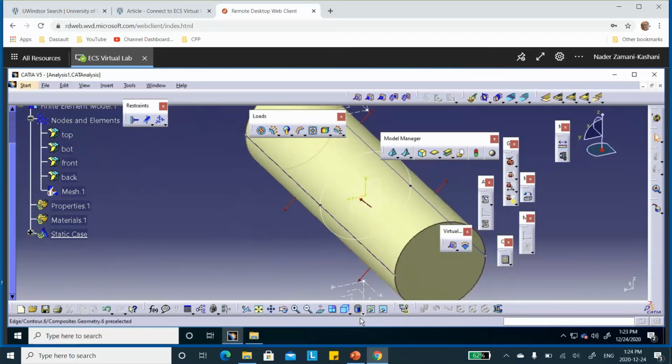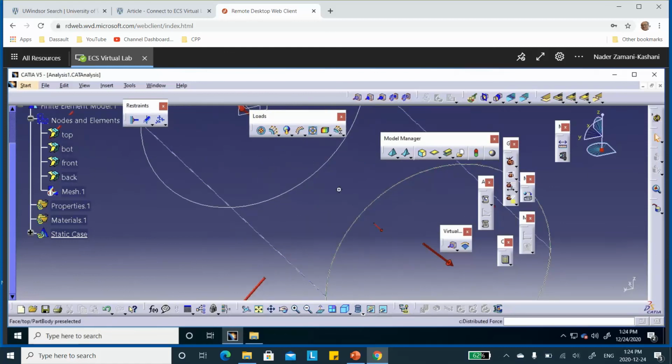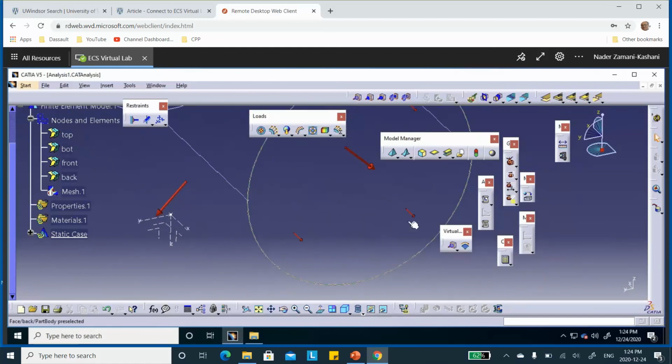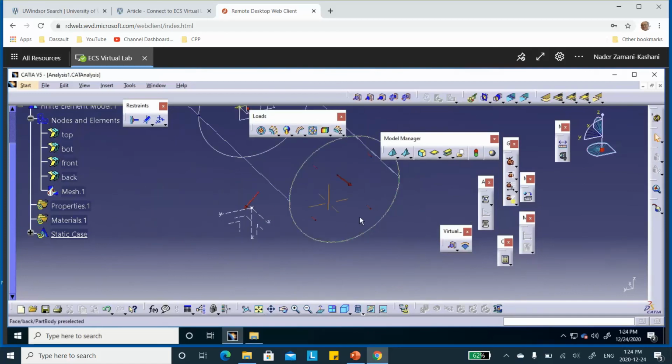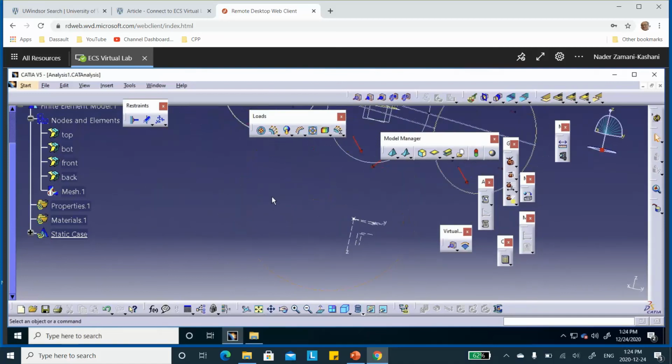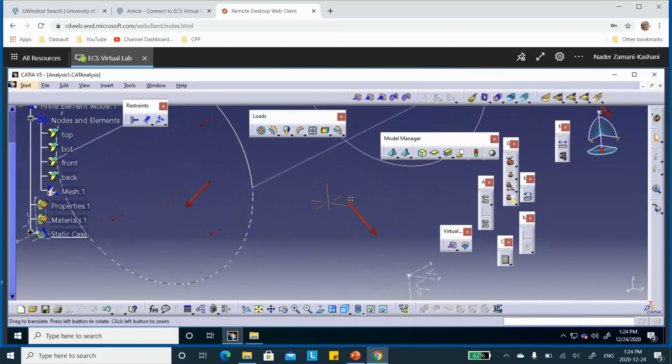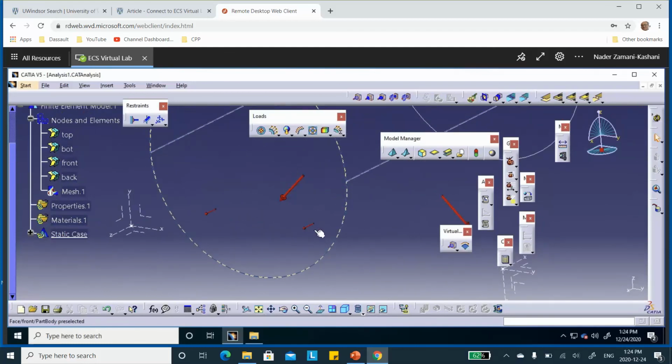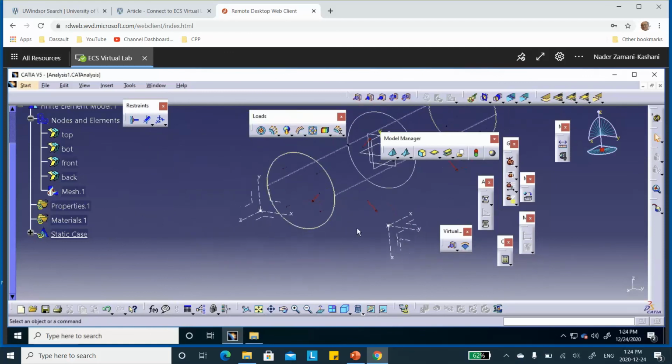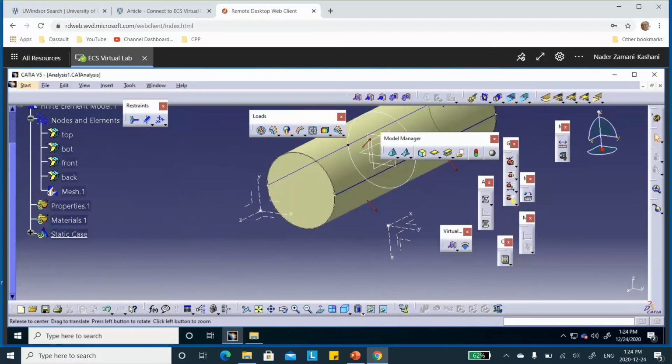So if you change this to wireframe rendering, you can see that they're all pressurized outward. Okay, see that? Outward, outward, outward, and the same thing over there. Had I fixed that by going and changing the direction of the join of that surface and flipping the direction, they would have looked a lot nicer, and I could have done all four of them at the same time. But that's life. Okay.